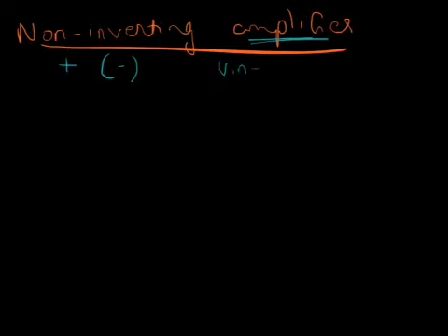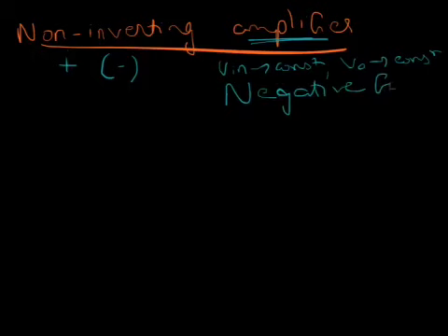If Vin is constant, we expect Vo to also be a constant, and so it is still going to be negative feedback. The feedback does not determine the sign of the transfer function. The feedback determines whether Vout is going to remain constant or not. And in this case, we want Vout to be constant, so we will put the amplifier in negative feedback.